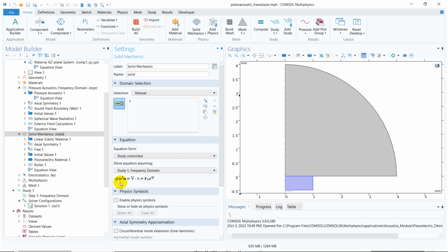That is why, if you see, this is the converted frequency domain solid mechanics equation. Again in solid mechanics, if you remember, there was the second derivative of displacement. That second order time derivative is converted into this omega square term, because with e to the power i omega t, if you do the derivative two times it will become omega square into u.